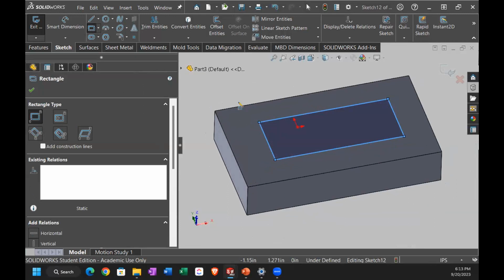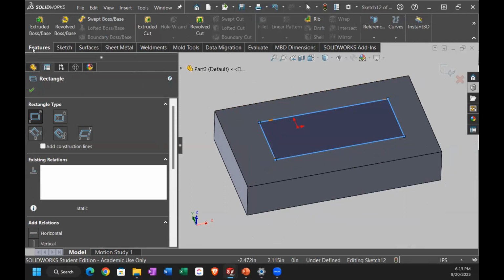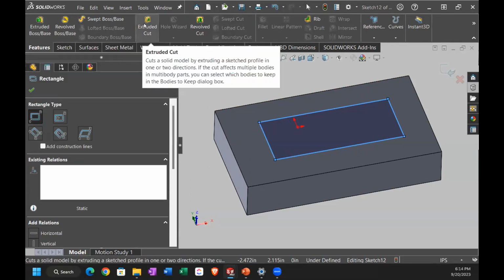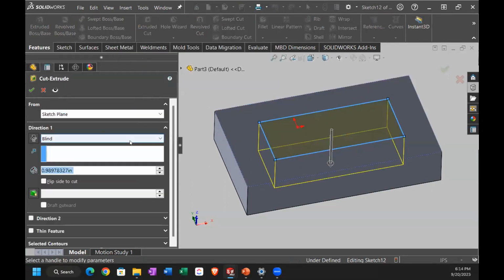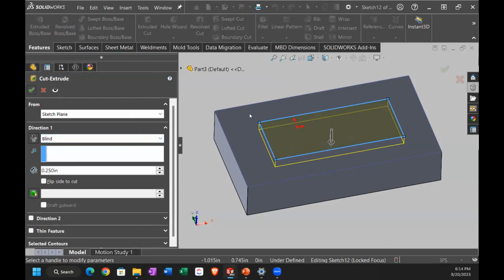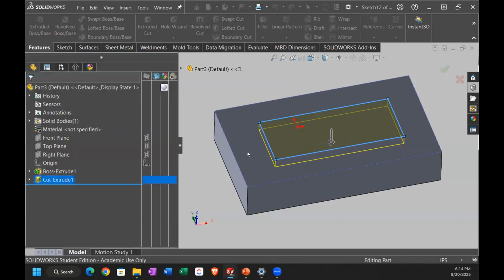All right, so round tools do not cut square holes. The standard process would be just to draw a circle. The problem with the circle is I've got to do a second operation. I don't like it as much. Those geometries do okay, but I have a preferred. So I want to make that a feature that I can drag and drop and use pretty much throughout.